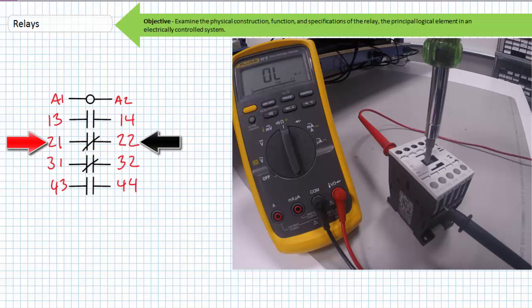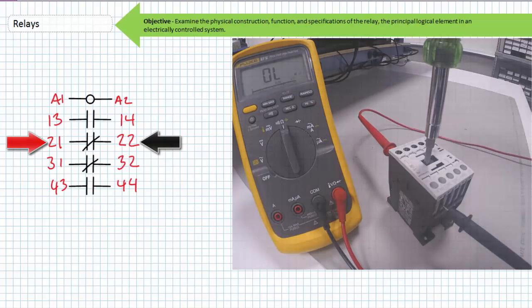One does not simultaneously go forward and reverse. Not only does this not make sense, it constitutes a phase-to-phase event in a three-phase AC electrical system, an event characterized by an arc flash hotter than the sun and a lab instructor whose anger is hotter than 10,000 suns. The mechanical interlock prevents this most heinous of actions from occurring.